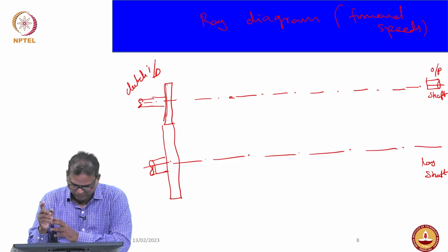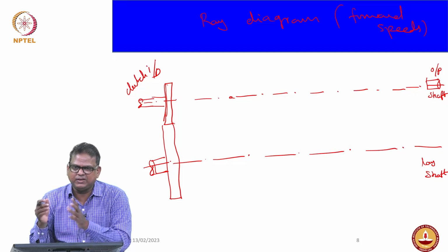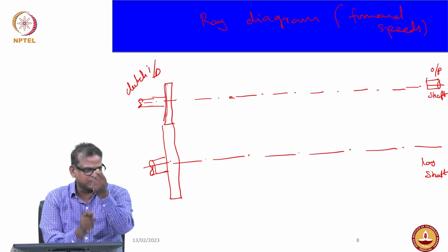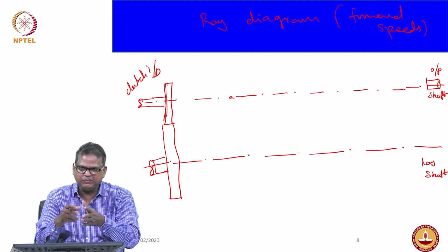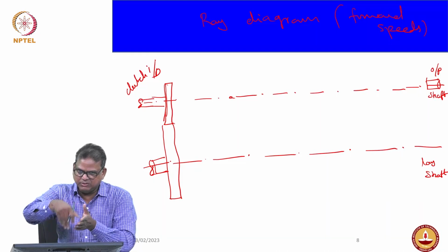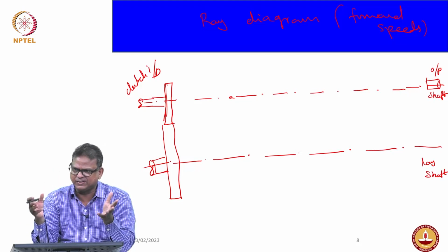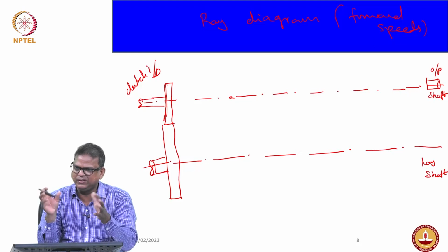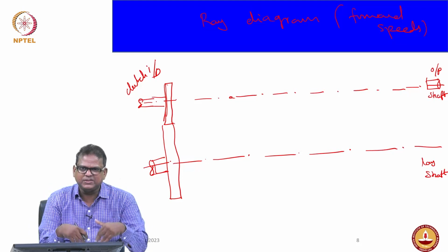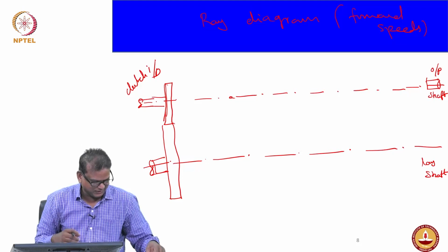Still one more piece of information we have not discussed. We have not considered the gear selection mechanism, right, because this is constant mesh. So in between you need to have a gear selection mechanism, the dog clutch, which will also be part of that. It should be common, because you don't want too many gear selection dog clutches; you need as few as possible. By doing that, you are again reducing the size and the mass of the gearbox.